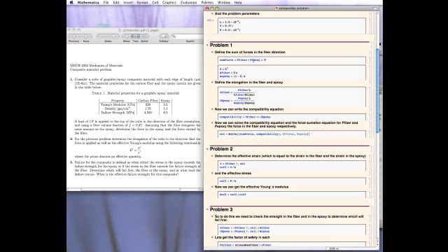All right. So first I write the force balance equation. It's relatively easy. So this here is actually the force balance equation. I'm going to give it a name, some force. Okay, so this is a little tag that just refers to this equation. But the equation is actually the load in the fiber plus the load in the epoxy has to sum to the total load applied. All right. Okay. I have the double equal sign to show that it is actually an equality that has to be enforced.